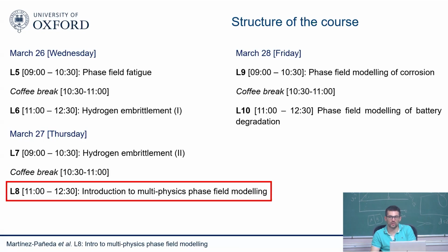So today I'll tell you in general how to deal with any multi-physics problem, and I'll provide some examples of implementation and describe, particularly in Abaqus, how you would implement some of these things. In places like COMSOL, it's straightforward, but the same way we do it in Abaqus, you could do it in any other commercial finite element package, or not commercial, anything that solves for thermomechanics, which is, I guess, all packages you can use.